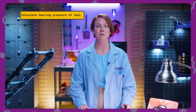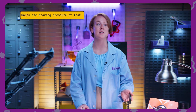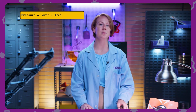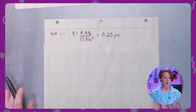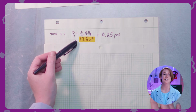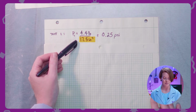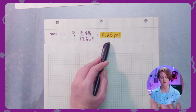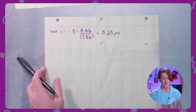So now that we have the max weights and the area for each test, let's go ahead and calculate the pressure for each test. Let's remember that pressure equals force divided by area. So for test 1, it was able to withstand 4.4 pounds of force over an area of 17.5 inches squared. That equals 0.25 pounds per square inch, or PSI.